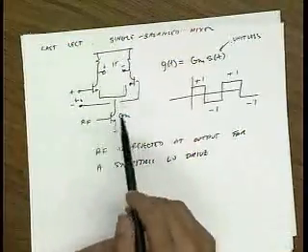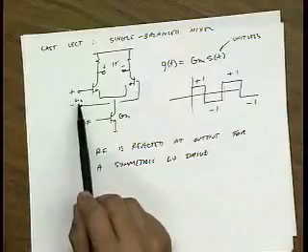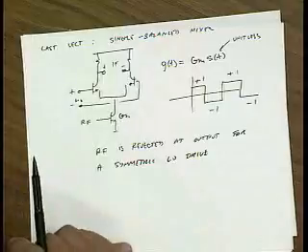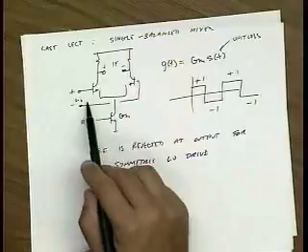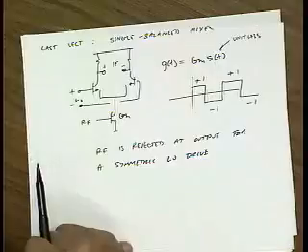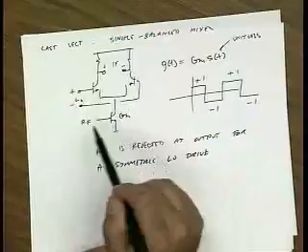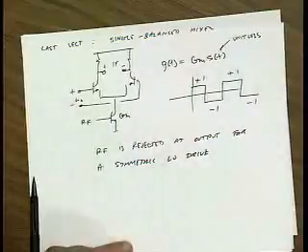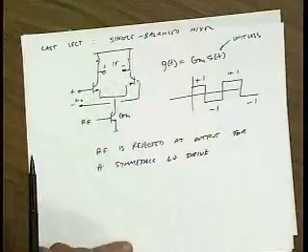What's also interesting is if you plot the noise figure of, let's say, this mixer as a function of the LO, you'll find that the larger you make the LO, the lower the noise figure. Okay? Initially that might not be very intuitive because you might think the larger the LO, the more harmonics I have, and so the more noise folding I would get, right? Which is true, but remember as you increase the LO, you also get more conversion gain. So perhaps those two things could cancel out. There's another factor that comes into play that actually dominates, and that's the noise of this switching pair itself.